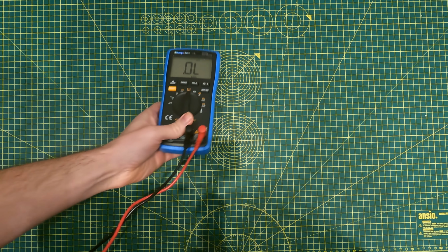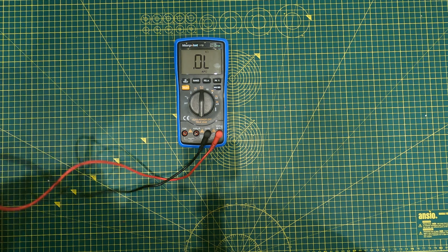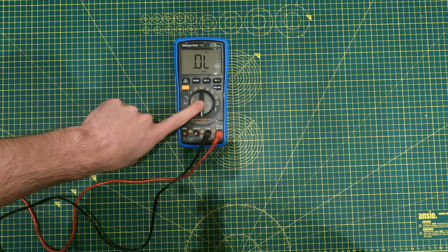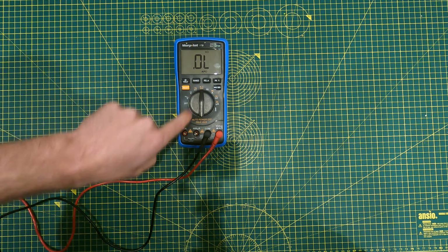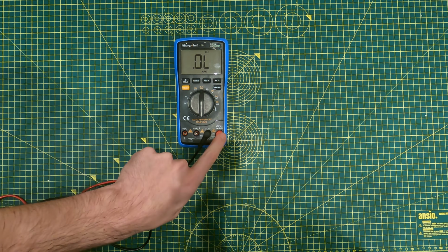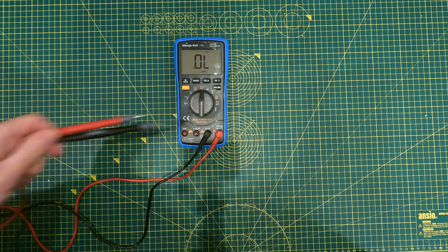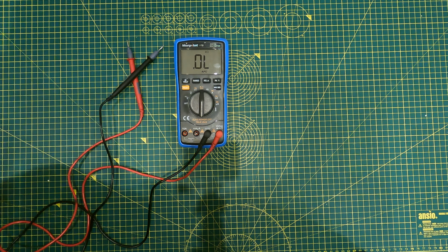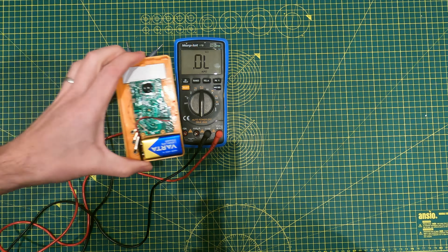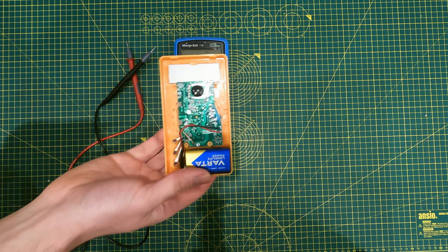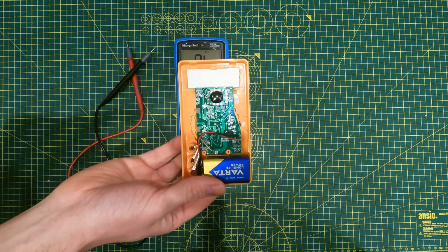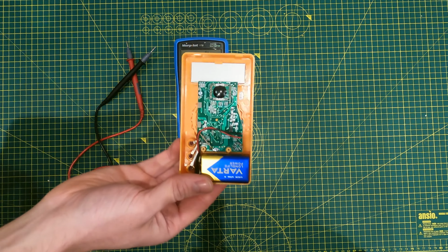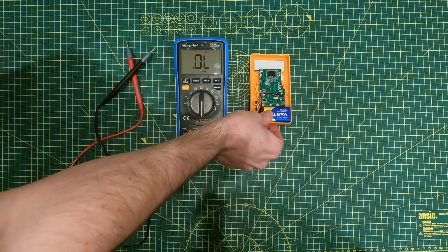Okay, so let's go ahead now and take a measurement of resistance. So as you can see, I've got the selector dial on the correct feature. I've got the black terminal in the COM and the red terminal where the ohm symbol is right there. And it's important to note here, whenever you're taking a measurement of resistance, pretty much all electronic equipment is going to be in parallel, so you have to isolate the resistor first.